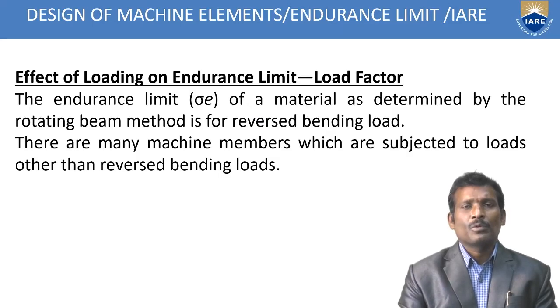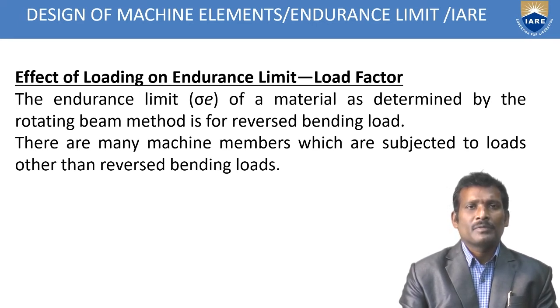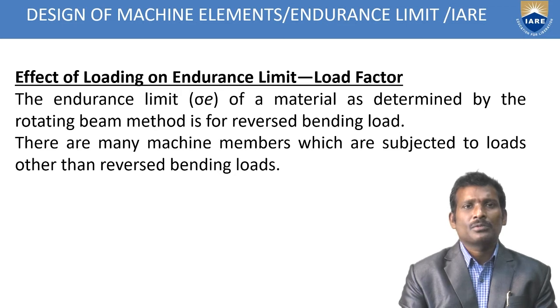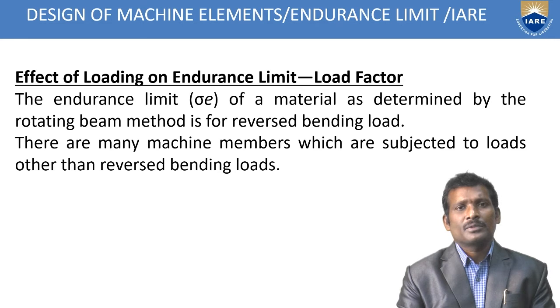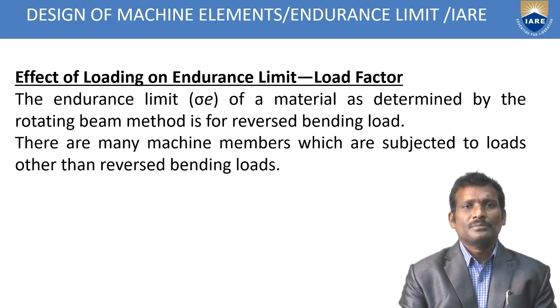What is the effect of loading on the endurance limit? That is called the load factor. The endurance limit of a material as determined by the rotating beam method is for reversed bending load. As per the definition of fatigue, whenever a component is subjected to repeated or cyclic loads, the component fails after certain intervals, and the stress at which it fails is below the yield stress.